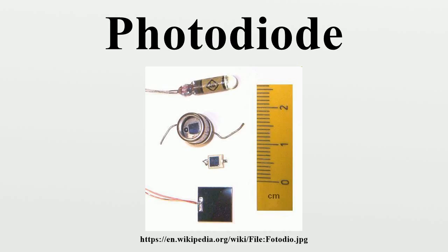The electrons that are generated by photons in the base-collector junction are injected into the base, and this photodiode current is amplified by the transistor's current gain beta. If the emitter is left unconnected, the phototransistor becomes a photodiode. While phototransistors have a higher responsivity for light, they are not able to detect low levels of light any better than photodiodes. Phototransistors also have significantly longer response times.